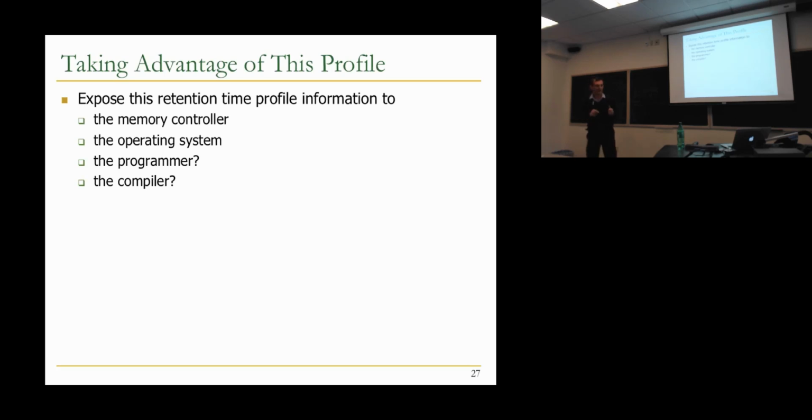For example, if the variable is really temporary, you could construct a row of variables that are really temporary and never refresh that row, because the variables are not going to be used beyond 64 milliseconds anyway. So you could come up with creative solutions like that if you have a lot of control on your system. It's not very general purpose.